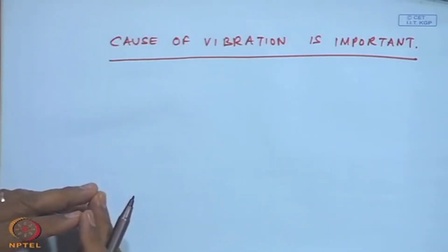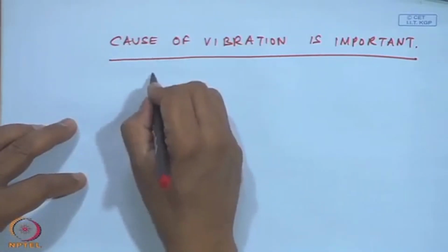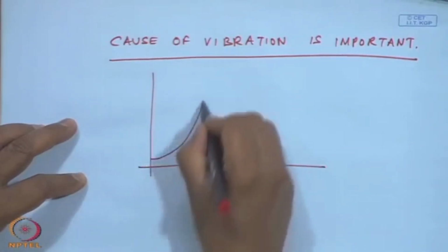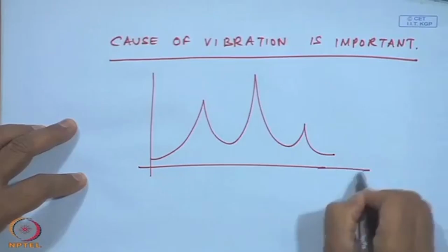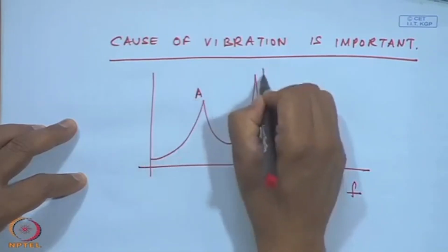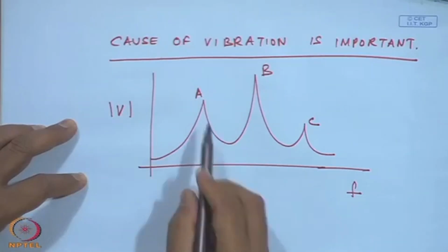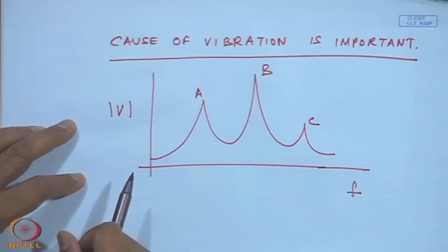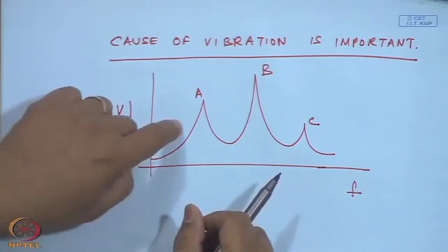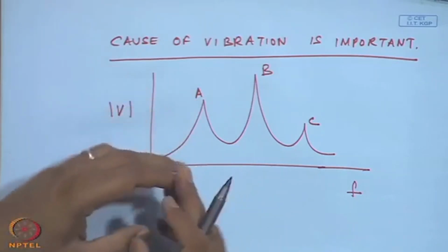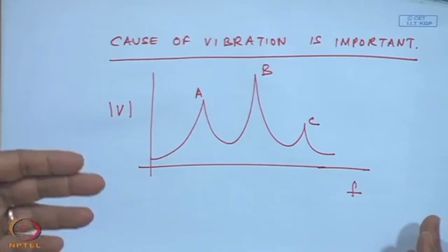Machines are going to give out vibration levels A, B, C, machine components at their characteristic frequencies. So, this information is not available if I just look at an RMS level of the vibration level from a permanently installed transducer. I will get a certain value. This only tells me whether the value is more or less than the acceptable level.